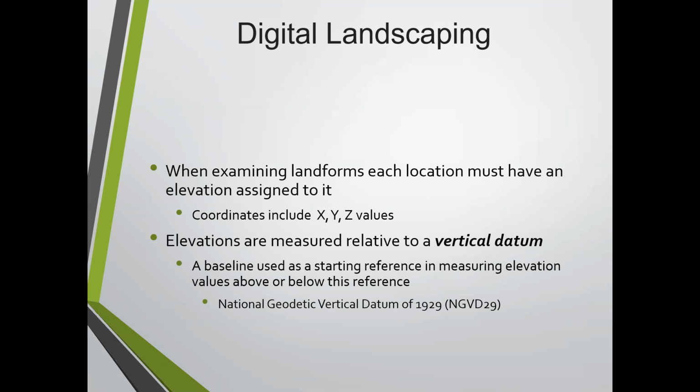Of course, we talked about the current datums that we've had, so the National Geodetic Vertical Datum of 1929, the NGVD. That's a dead system, but it was actually still used by certain branches of the feds. I think FEMA was still using it not too long ago. And then this is the newer one that superseded that, and we've talked about all of that. And of course, we have the new one that's coming out, 2022. So that's going to change things again.